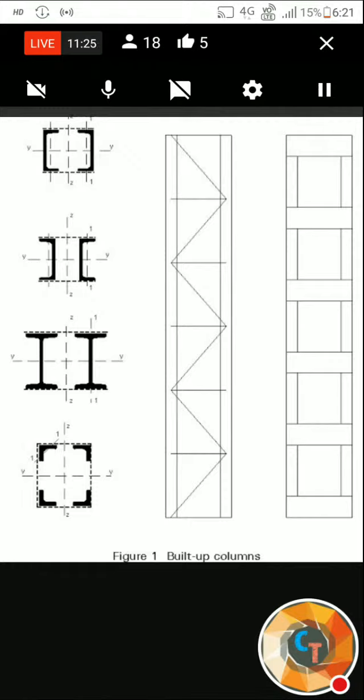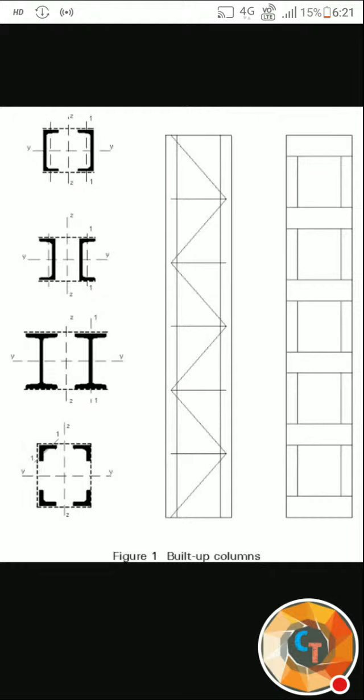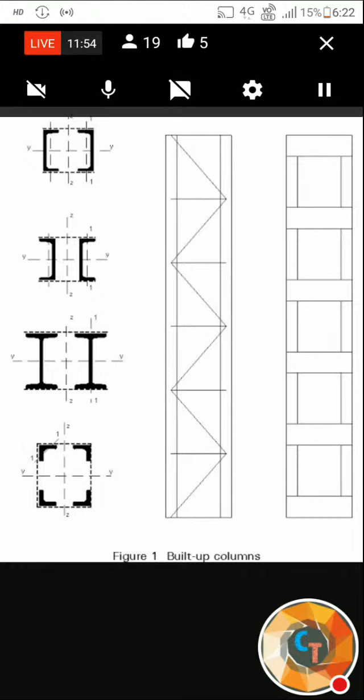Sieve size, you are correct. It is on sieve size, but at what sieve size will you find out? If the fine aggregate passes 4.75 mm, it is treated as sand or fine aggregate. There are four zones in the same sand. Whatever material is less than 4.75 mm is treated as sand itself, right? So why have they made four zones in that? On what basis have they made them? Fineness modulus, 100% correct, Ashwini.